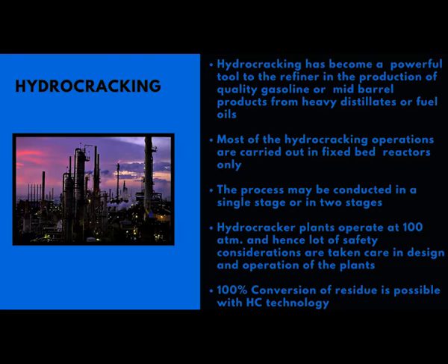So, primarily the cracking happens using three different techniques. Each one has a certain value addition in terms of percentage. For example, a thermal cracker can convert almost 50 to 60% of your residue into valuable products. The next one, the fluid catalytic cracking unit, can convert 70 to 80% of your residue into valuable products, whereas a hydrocracker unit can convert almost 100% of your residue into valuable products, but of course it is a cost-intensive unit.